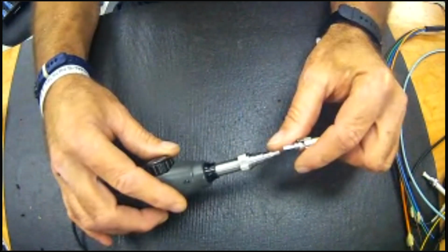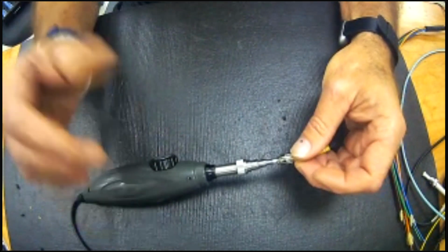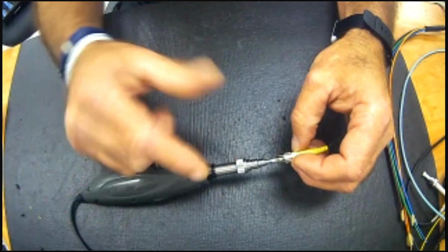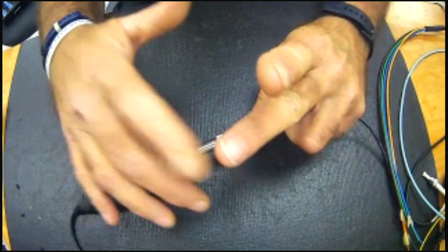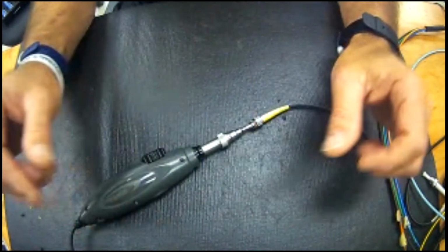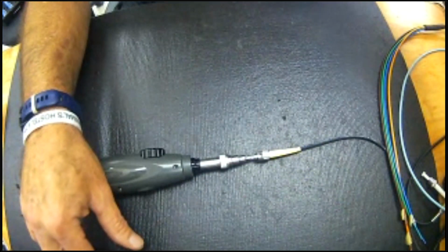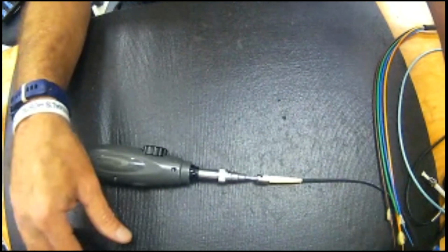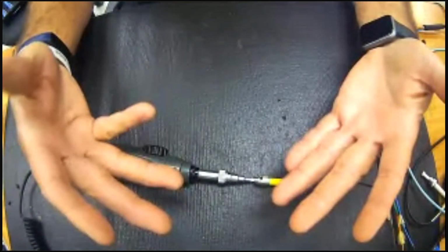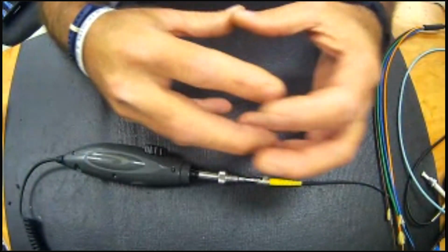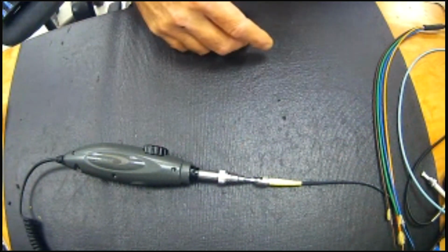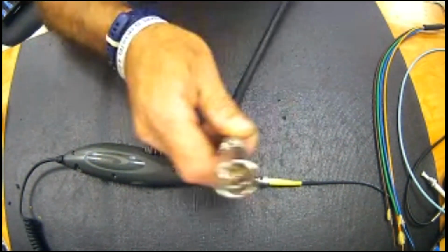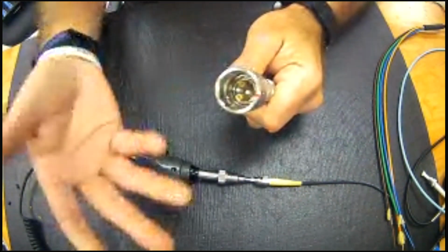A video scope gives you the ability to plug the connector in the end, and in my case, it's plugged into a laptop. I get to look at a big, bright image. I get to look at the quality of polish. I get to clean my contacts. In addition to that, the contacts inside of multi-pin connectors, hybrids such as the Limo SMPTE, are embedded down inside the connector. You don't get to go there and get to them,